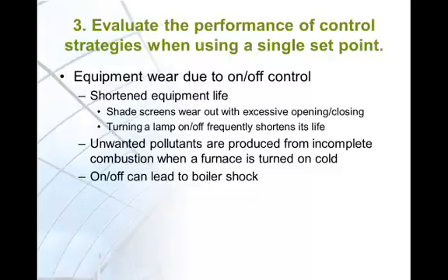Boiler shock is when the return water is coming back to the boiler at a relatively low temperature. This temperature difference, with the hot boiler and its contents, can create significant stresses on the boiler components and may result in premature failure. The solution is to incorporate a way to control the temperature of the return water. On-off control typically does not allow for fine control, such as regulating the water temperature. We typically use mixing valves for this purpose, and they need proportional control at a minimum.